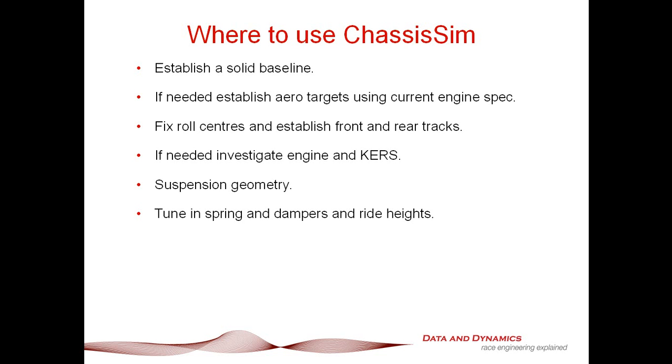But that process there: you establish a solid baseline, you fix your aero targets, fix the roll centers, play around with your tracks and wheelbases. Again, don't forget your moments of inertia. Move on to your engine and curve stuff. Move on to your suspension geometry. Then tune in with spring, dampers and ride heights. And I really can't ram that point home enough.